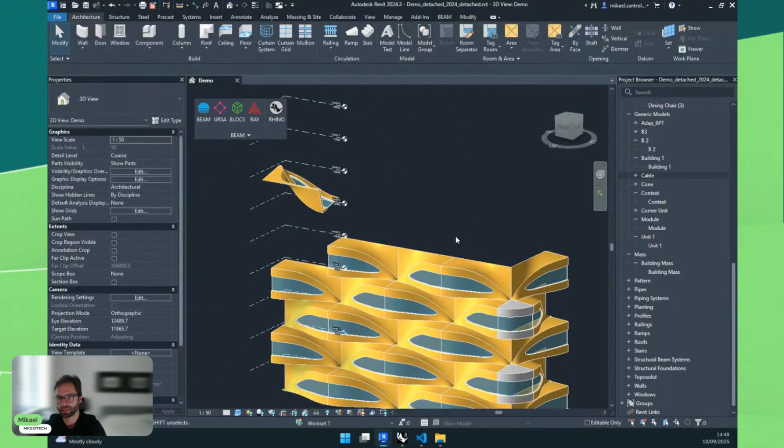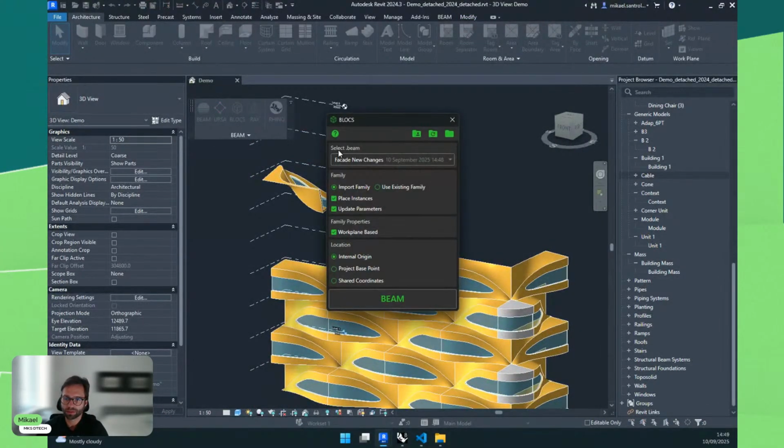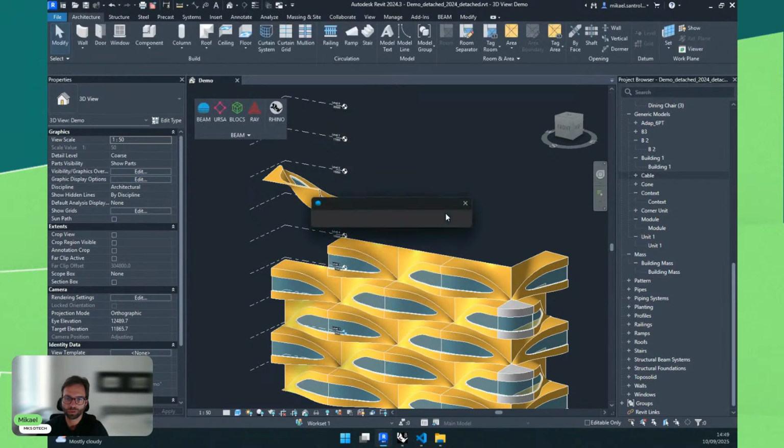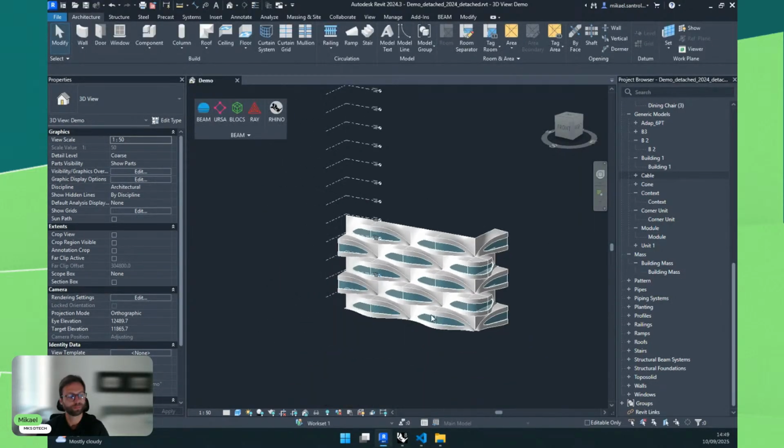So let's delete this that is new, and as always, we can go back to the V1, which will go back to that specific point in time. Perfect. So that's a way to use blocks and update block locations. You can move around your blocks, and you will move around the instances in Revit.